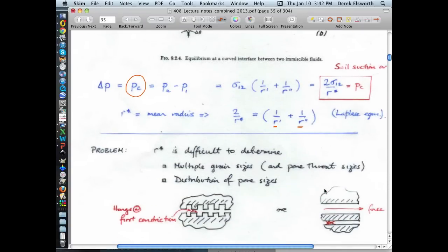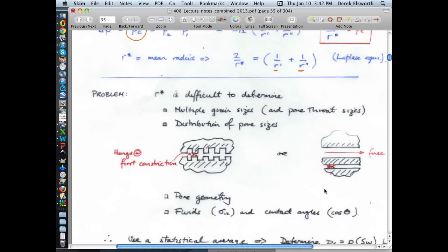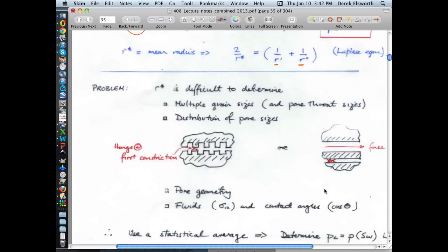And we can look at bundles of these capillaries to look at the kinds of pressures that we'd have to apply to push these fluids through a porous medium. And we can think about arranging these as a whole bunch of capillary tubes, if I had another pen, a whole bundle of pens, where these pens might be wide and very narrow ones, in which case we could guess that if we had a whole bunch of narrow pens, the stuff would get hung up in these, but if we had a whole bunch of open capillaries, then it'd be happy to go through there, even if we put a small amount of pressure on it to push it through there.